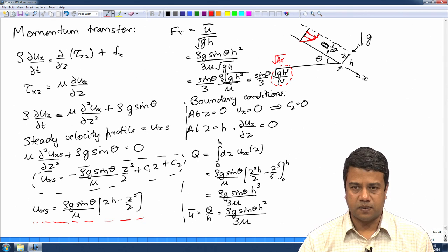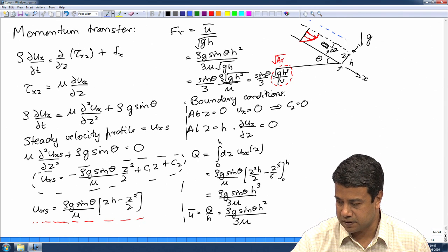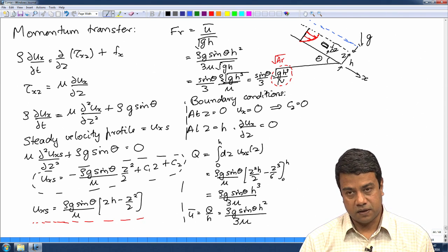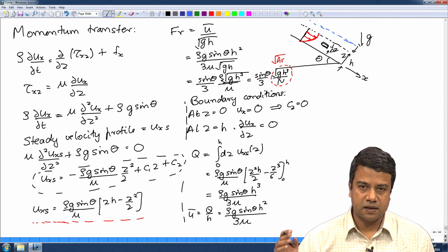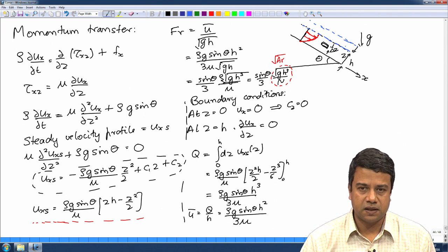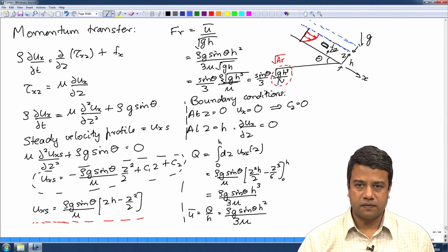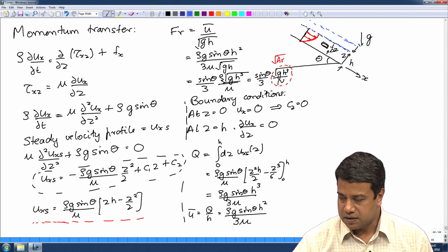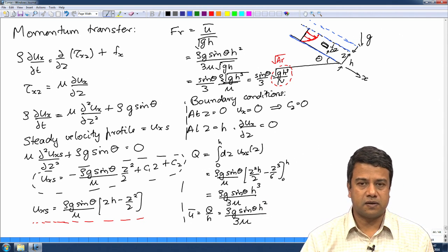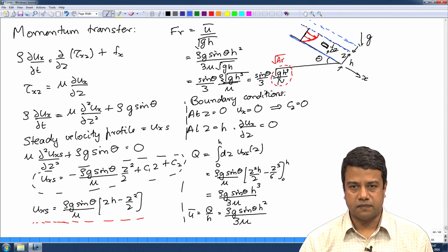You could think of more complicated problems. For example, you could think of a film that contains 2 fluid layers. In this case, you will have 0 velocity gradient at the top surface. At the interface between the 2 liquids, you have to have equality of velocity and equality of stress. Zero velocity boundary conditions at the bottom, and zero stress boundary conditions on the second layer on top. And you have to solve all of those simultaneously in order to get the velocity profiles.